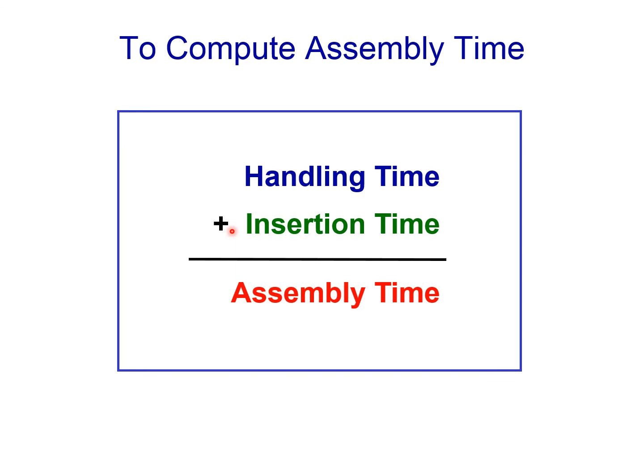So the idea is engineers have a candidate design and they do this computation and it calculates an assembly cost. Then they do a redesign and compute the assembly cost again and take the cheaper one. It is not a whole lot deeper than that. The software works by asking designers a series of questions about their design to estimate assembly time, such as, can you do it with one hand? Or do you need two hands for manipulation? Or do you need two hands because the part is very large?